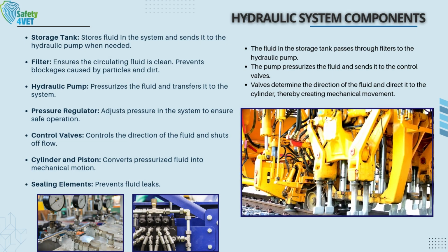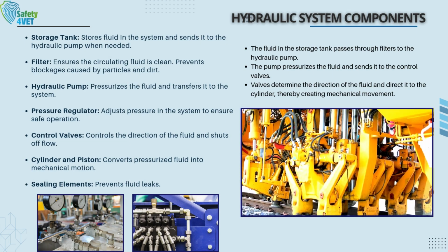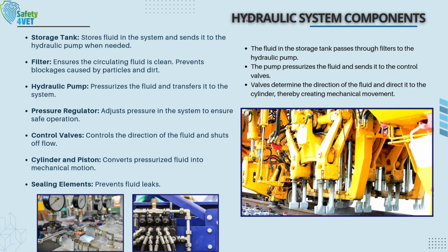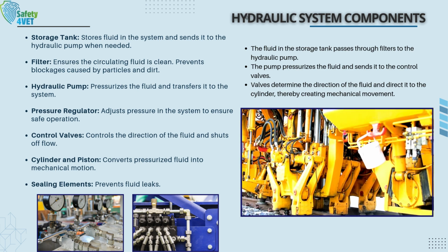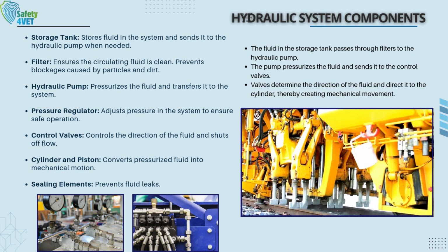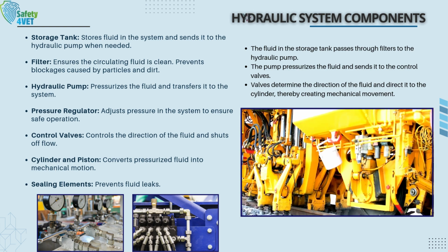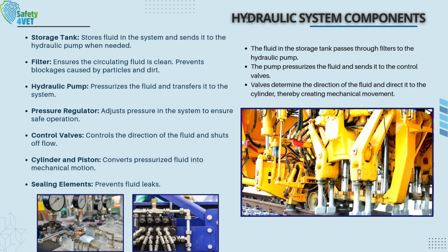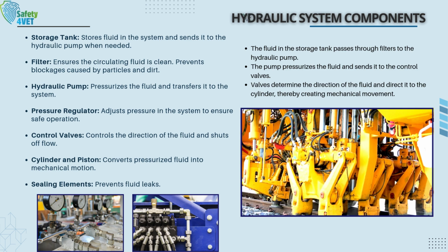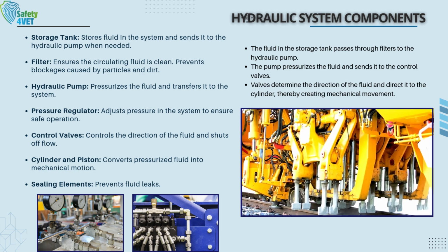The fluid in the storage tank passes through filters to the hydraulic pump. The pump pressurizes the fluid and sends it to the control valves. The valves determine the direction of the fluid and transfer it to the cylinder, producing mechanical movement.